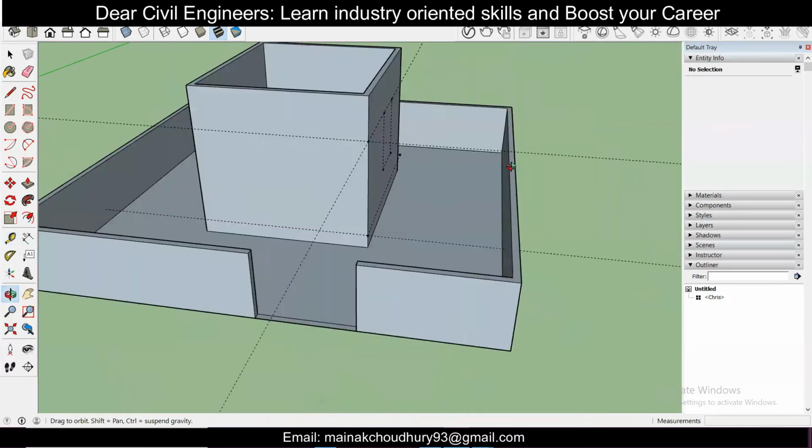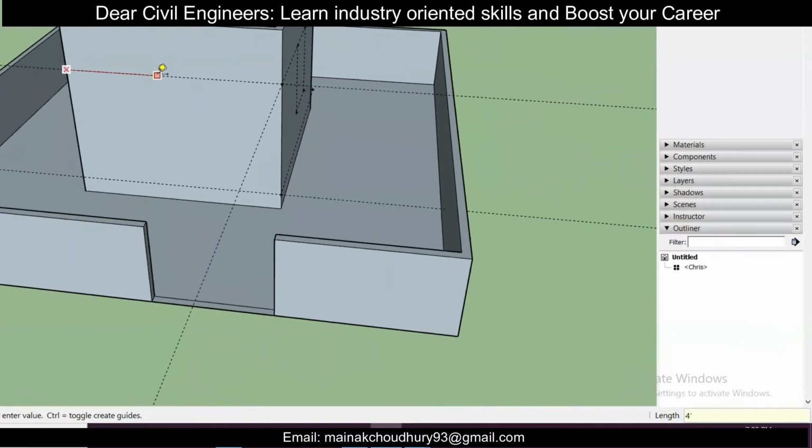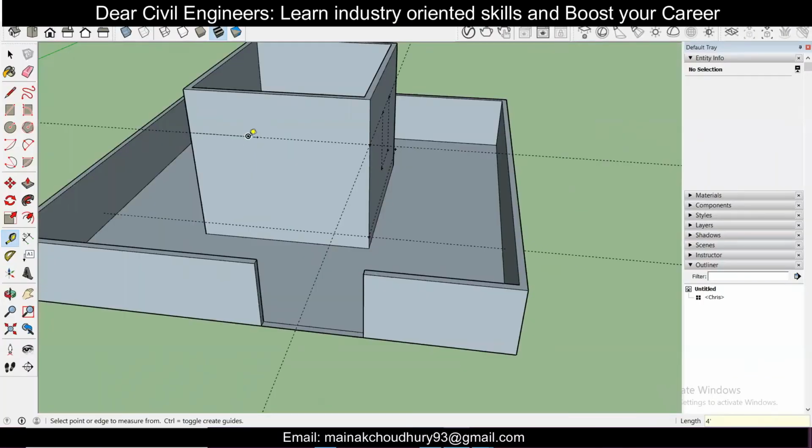And let's also provide the opening for the door. So we'll measure it. As you can see, this appears on the screen. This is 12 feet, or let's go 4 feet, and then provide the door. So we'll type 4 feet, enter. Got this. And we'll just draw the straight lines. So it's along the blue axis.